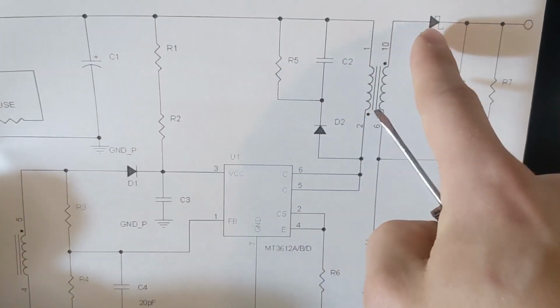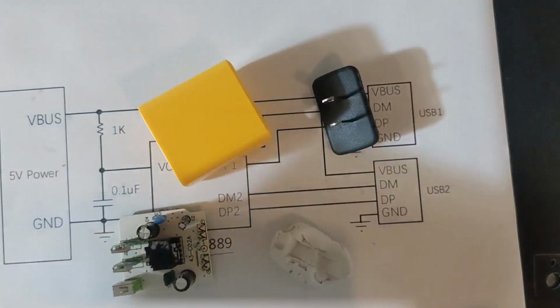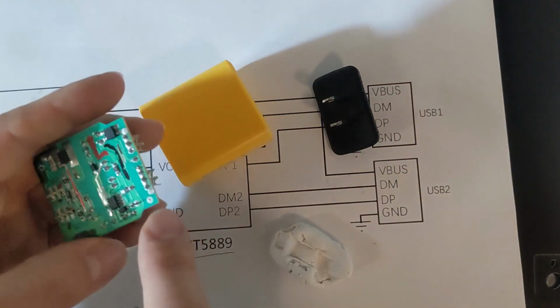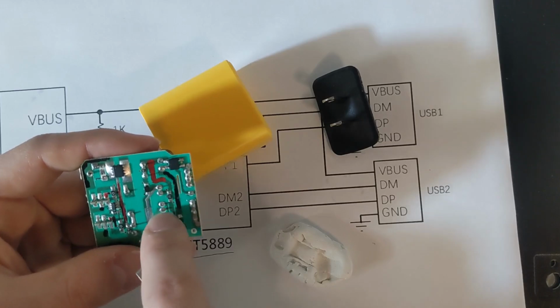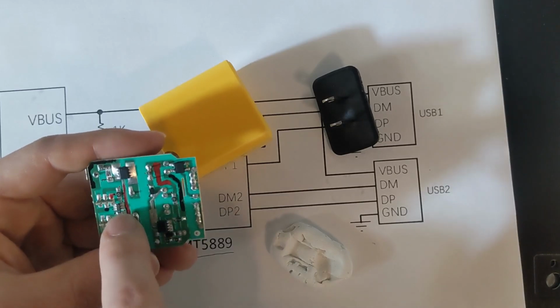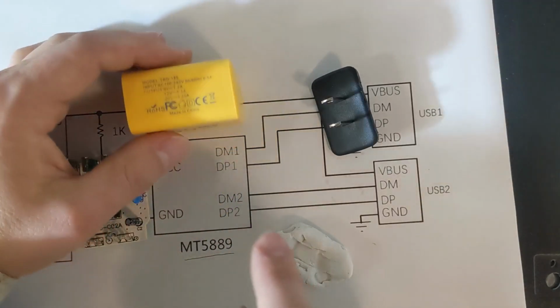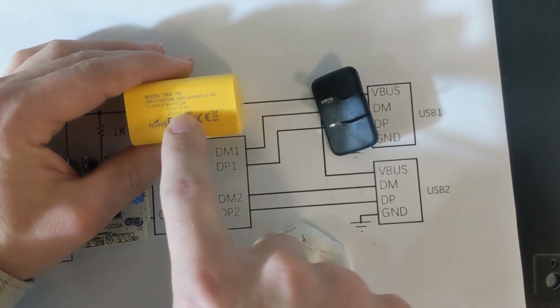And then you got an output rectifier here and some output caps. And this is almost basically identical to what they have here. They've got the transformer, there are 2 windings, so this is one winding, and then there's an inner winding, and then you got the chip. Based on this, we know right away, it says 9 volts, 7 amps, 12 volts, 5.4.